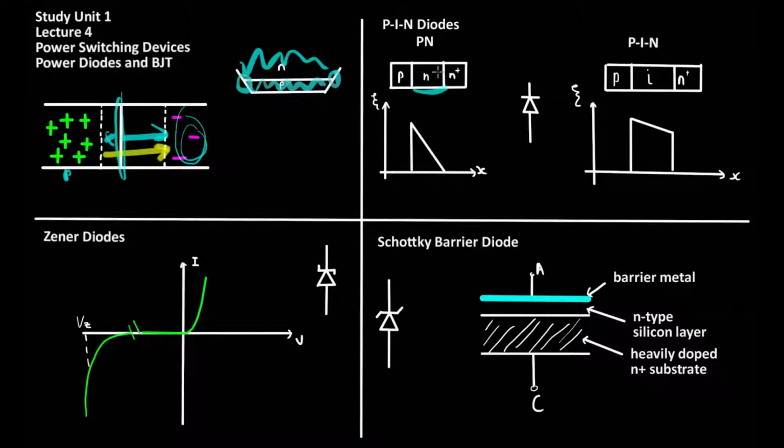The doping profile in this region can be customized to have a certain electrical field distribution. So in this example here, there's a very sharp fall off across the doping region, whereas in this example over here, the electrical field strength falls off more gradually between the n and p regions. This intrinsic region is normally modeled as a low concentration n-type region, which is sandwiched between the p and n regions. The low doping concentration of this intrinsic layer allows the space charge layer to extend across the layer between the p and highly doped n regions.